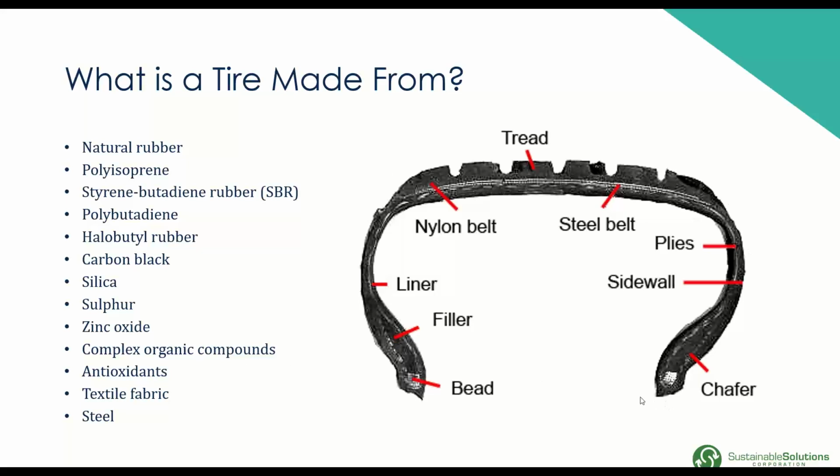When we're doing LCA, it's critical to understand what's going into this product. This is where the data collection really comes in, and we have to get down to every ingredient we can. We could obviously have cutoff rules where there are some things we just cut out, but we then want to understand what all the raw materials are and how we run the LCA.